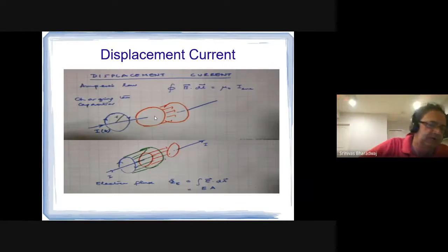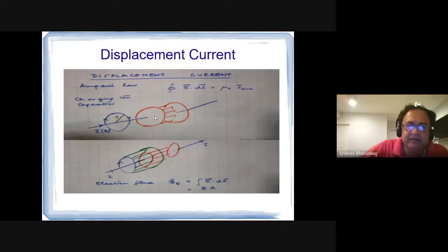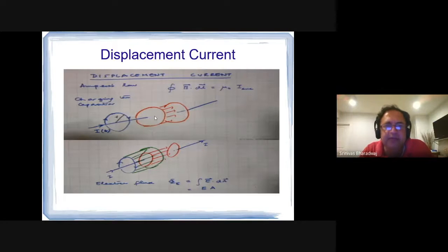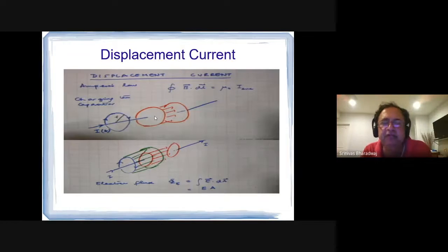When we normally talk about an electrical circuit, we normally talk about V equals IR, which is what? Conduction current, right? Current produced in, say, a metal wire. Now, if you had a capacitor in that wire and you ended up charging and then discharging that capacitor, it happens without the flow of charges through. There's no conduction through the capacitor. There's a form of what is called displacement current. Polarization leads to the current.